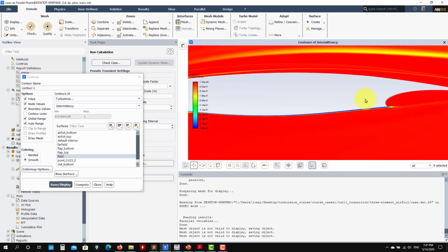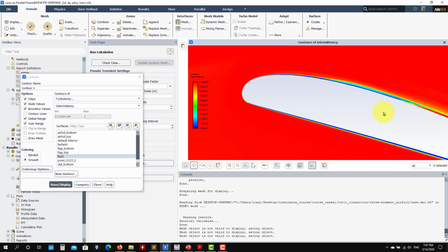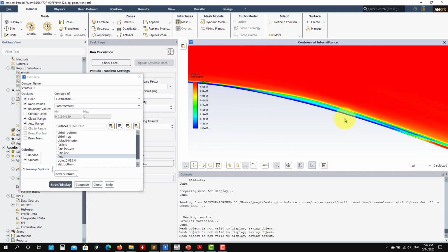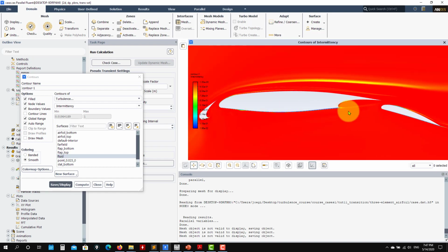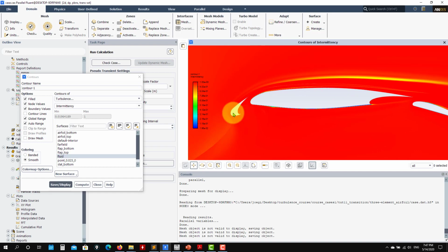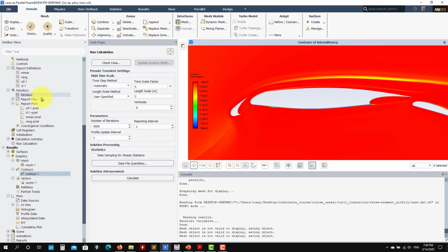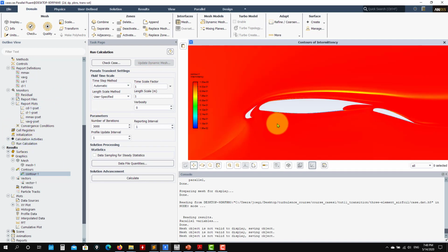And then we move to the flaps, and the same idea, okay? So at the bottom you have laminar flow, since this is a favorable pressure gradient. Remember from aerodynamics, usually when you have favorable pressure gradients, the flow stays laminar, whereas here there is an adverse pressure gradient, which will permit separation. So the flow is coming in this direction. I think it's what we call slide 13 or 14 degrees. In any case, you can compute it from the inlet conditions.